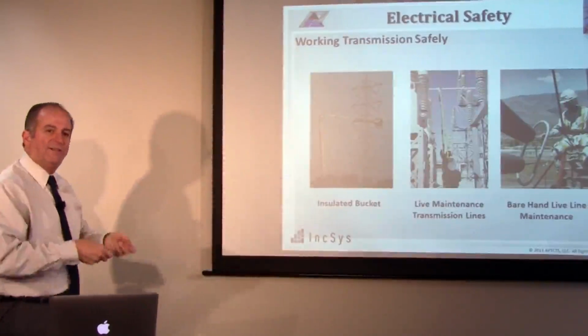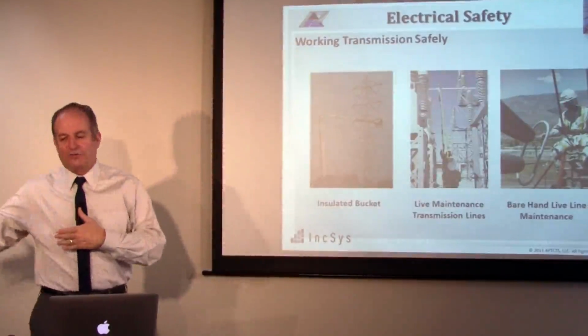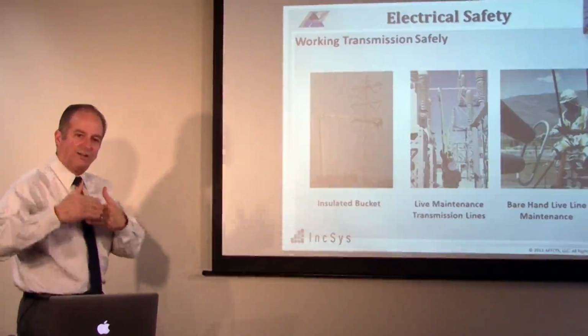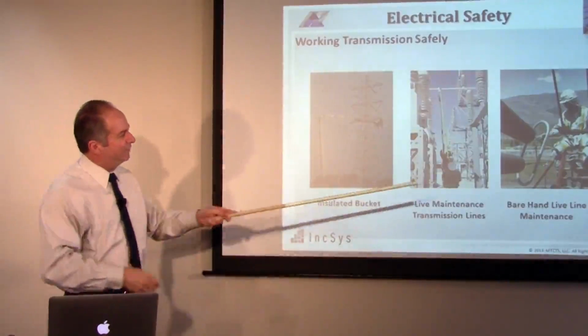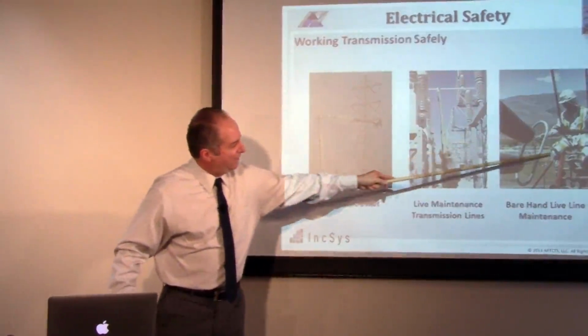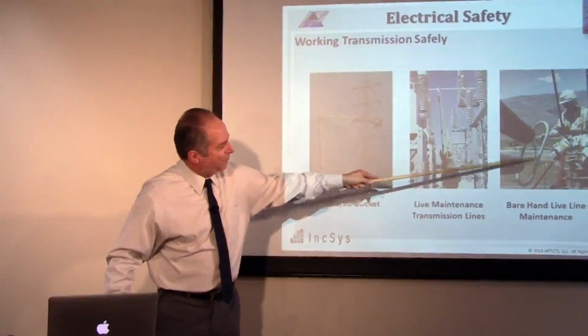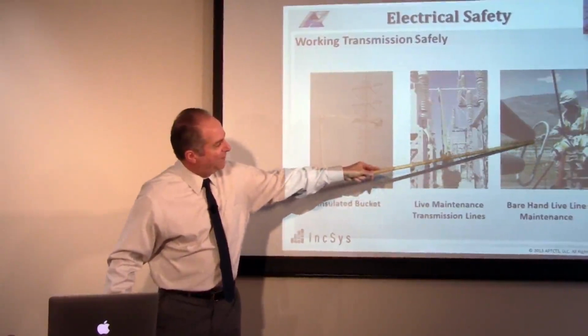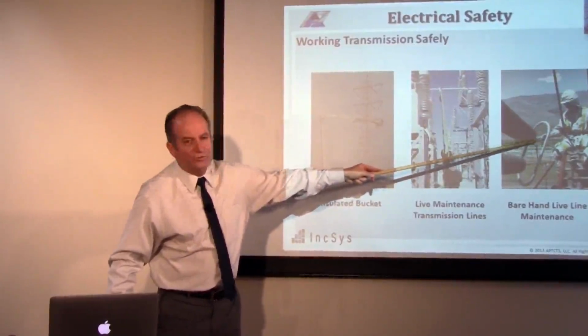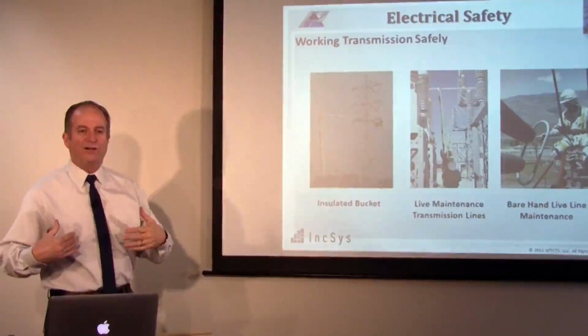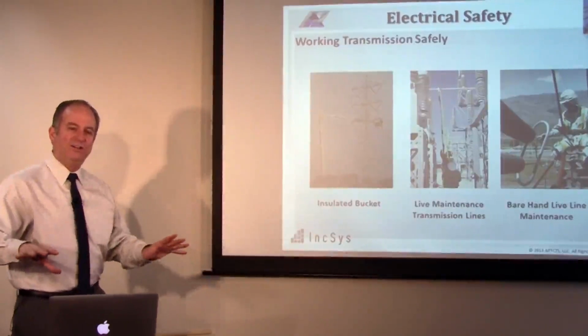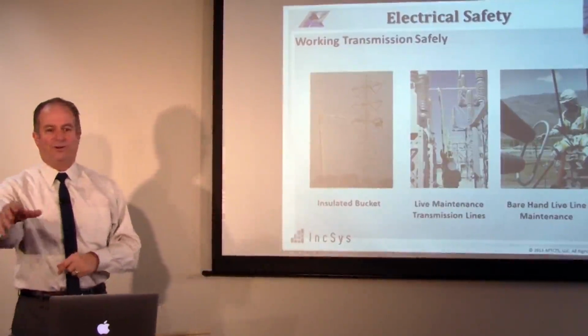And I shimmy out on that ladder, and then that ladder gets swung into the energized side of an insulator string. And I'm taking the insulated gloves, and I've got a lanyard there with a clamp on it that I'm actually clamping onto the energized conductor, and that's putting me at 345 kV, just like the line. So at that point, there's no sparks, no arcs, no nothing.